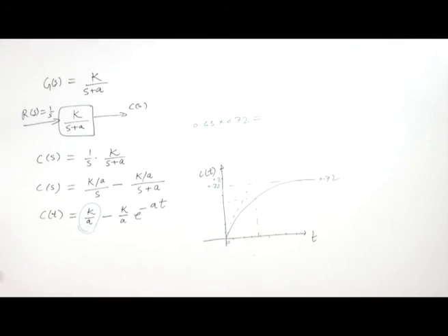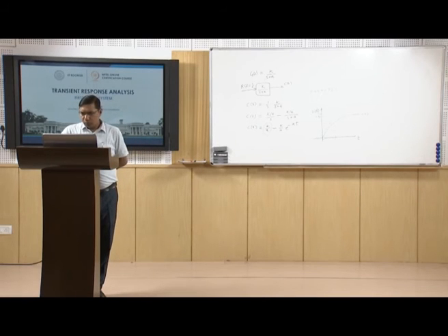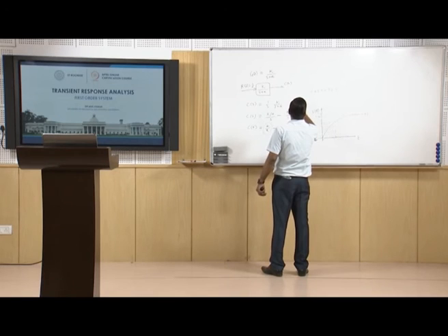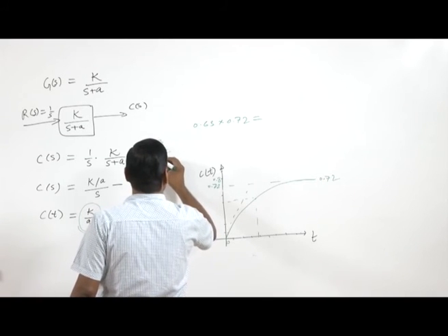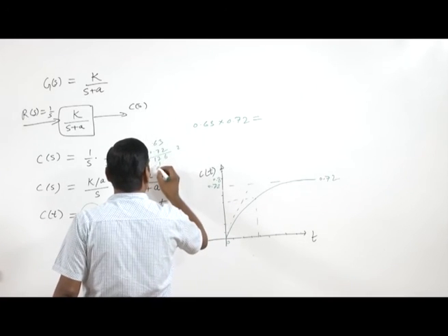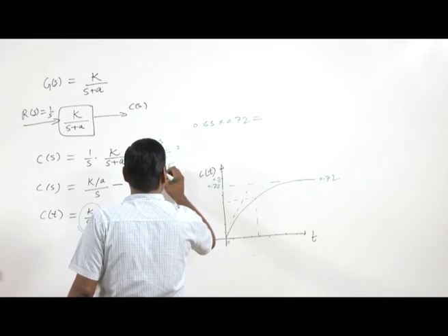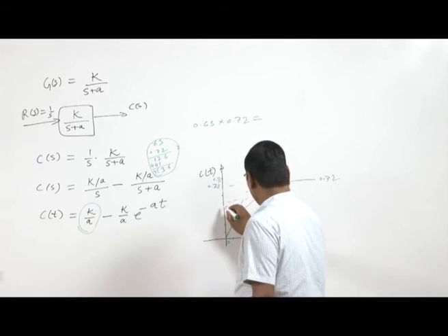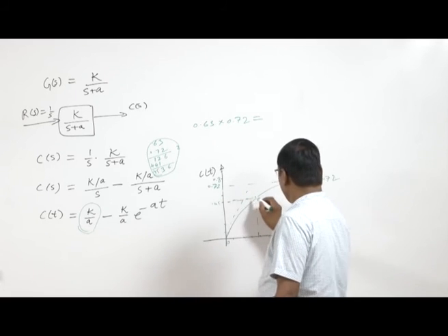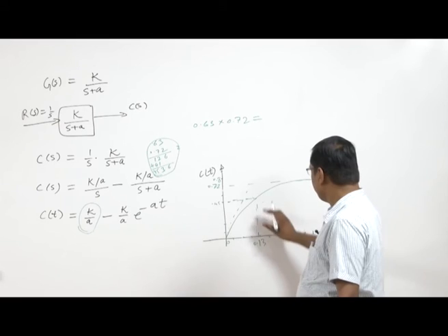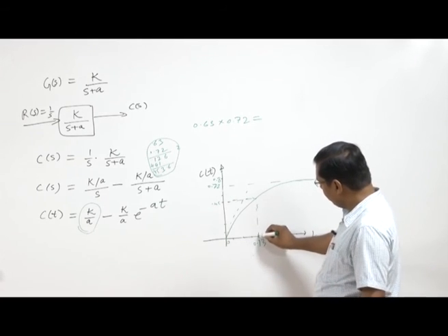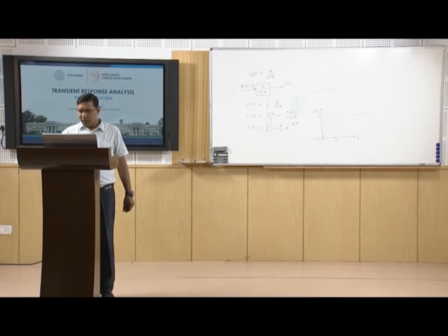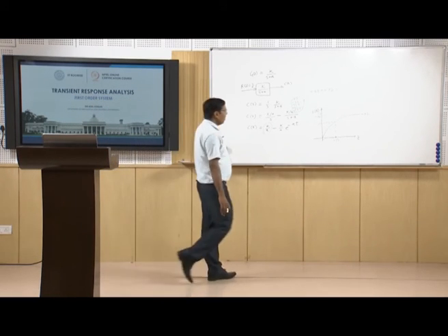So we can see here, it is about 0.45. So when we have something about 0.45 and here we have some time, so the time about this 0.45 will be the time constant, because 63% value of the final value.